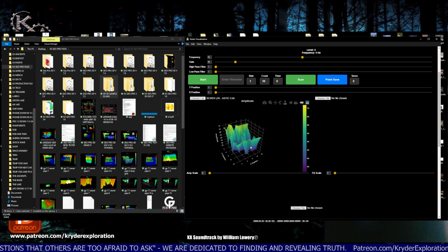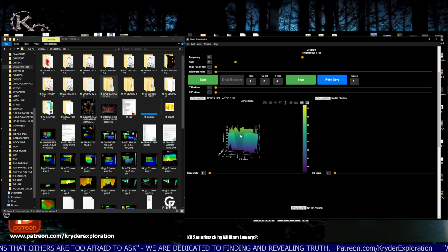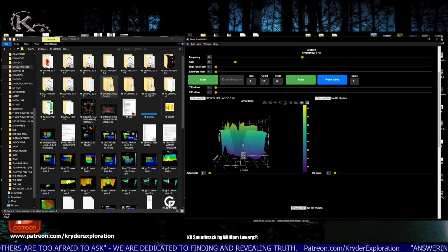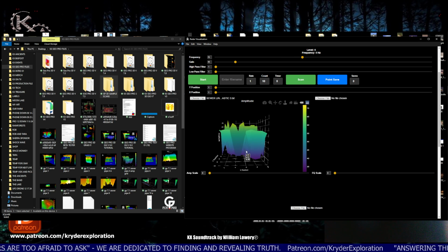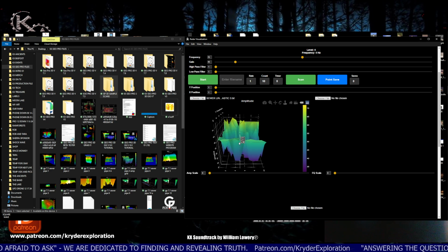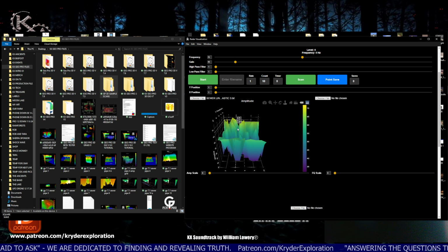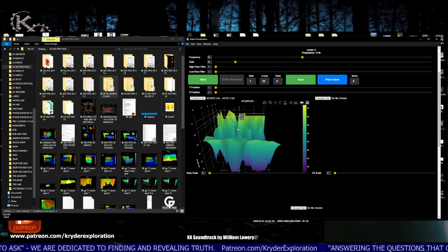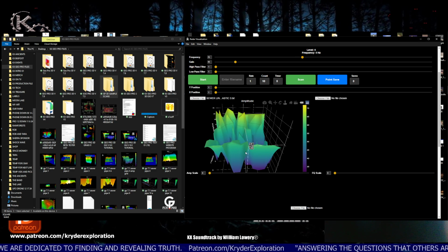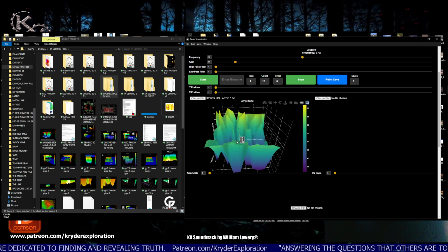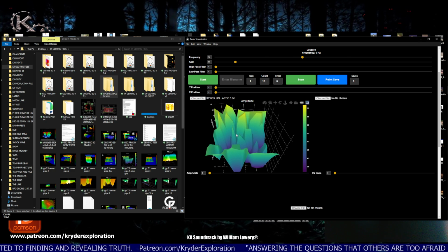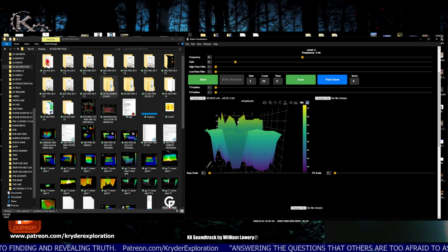Just to show you right off the bat, this is actually the signature from the ditch itself, this backfill signature. And then this V is being caused, and you can see it stripping all the way through here, because there's a low magnetic field there. That's actually the plastic pipe. So you basically have the ditch, the backfill, and the plastic pipe runs right through there at 4 inches. That's basically what we call a gap in the data.